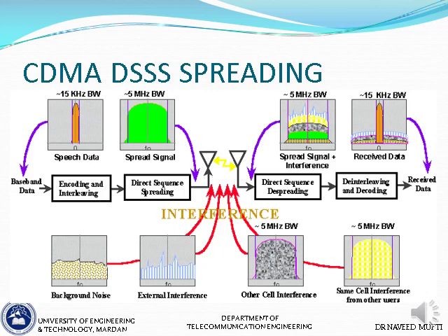Okay, so first a little bit of further insight into CDMA. As you can see, this is a very graphical explanation. So we have our baseband signal, our speech signal, let's say, occupying a bandwidth of approximately 15 kilohertz. That's our speech signal, and then in the direct sequence spread spectrum, it is made to spread. As you can see, it is a spread signal now occupying a bandwidth of almost 5 megahertz, which is the typical bandwidth of a direct sequence spread spectrum channel.